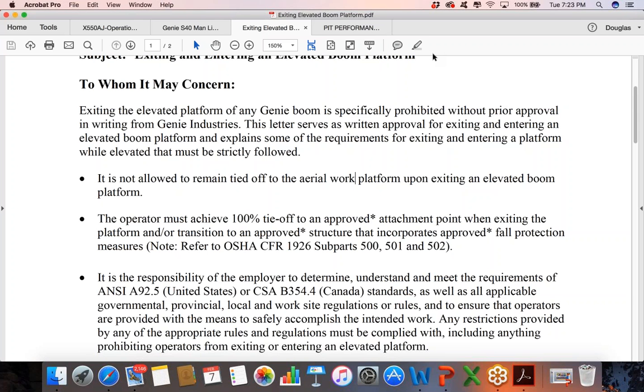Also, long sleeves and a closed shirt collar, right, to make sure that it's tightened up as much as possible. And then also worn clothing, right? The clothing can't be worn out. It can't be frayed. Why? It's another significant fire risk. Okay. Also, footwear. What are we looking at?